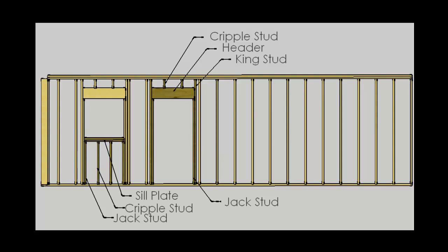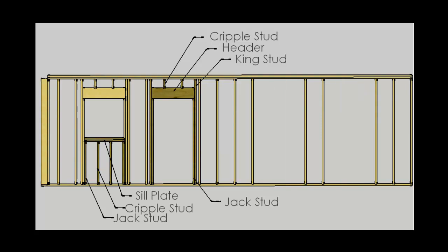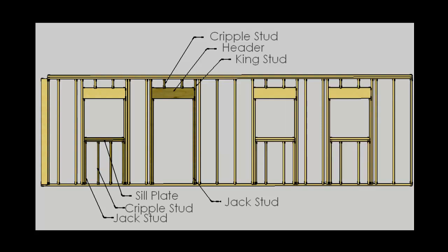Now, that's really all there is to creating a window opening. Very much the same as a door, just some added elements. So this can be a repetitive process from one window to the next. One thing that should be noted is depending on the load that needs to be transferred through the wall system and the size of the opening that we're creating, more importantly the width of the opening, there may need to be multiple jack studs on each end of the header to help support that additional load. Other than that, the process that we've gone through is exactly the same.